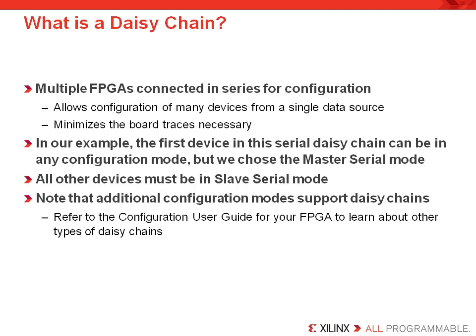Many customers have told us that when it comes to their preferred training experience, they want to be challenged a little bit. Well, we're about to challenge you. This next example is about daisy chaining. I want to first note that this is not the only daisy chain you can build. You can learn more about other daisy chain configurations from your device family's configuration user guide. But for now, we want to introduce the concept because daisy chains are used to manage your configuration resources, and daisy chains help you minimize your board traces and minimize the number of PROMs your system will require.